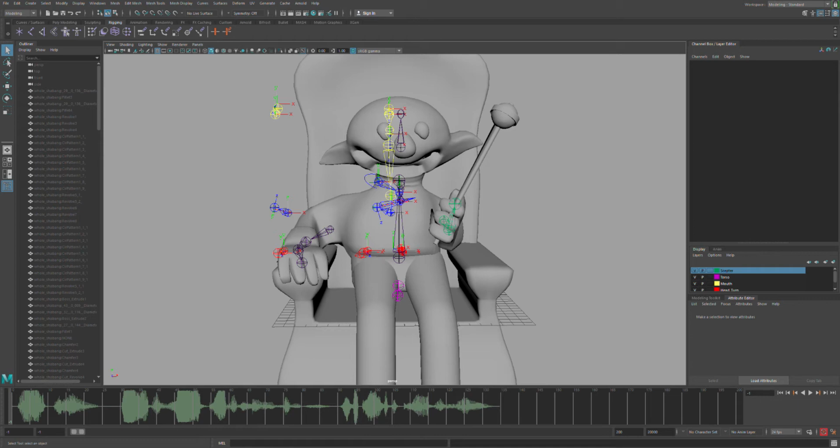And this video talks about how we have used the animation converter given to us by Weigl Show Control Systems to convert the animations from Maya on a 3D model into data that is recognized by the motors on our animatronic, which allows us to transfer the animations created in Maya to our animatronic in reality.